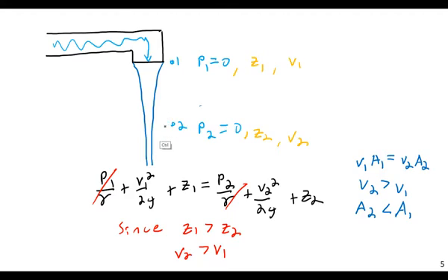And then, in order to preserve the continuity of flow, the continuity of flow rate Q, the velocity has to increase as it falls. The velocity will increase because of Bernoulli, but in order to keep the continuity of flow conserved, the cross-sectional area must decrease. Again, for a fluid with very low internal cohesive forces, it wouldn't necessarily have to do this. It could just turn into a spray or a foam or something. And in fact, water at very high velocities, that's what it tends to do.